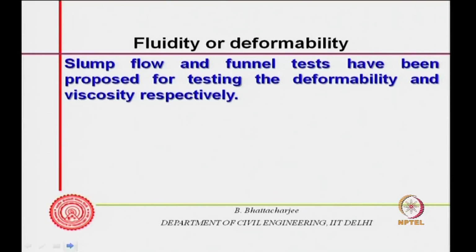This test gives us self compactability, but slump flow gives us fluidity and deformability. So, two other tests, one the slump flow test and the other the funnel test, have been proposed for testing deformability and viscosity respectively.